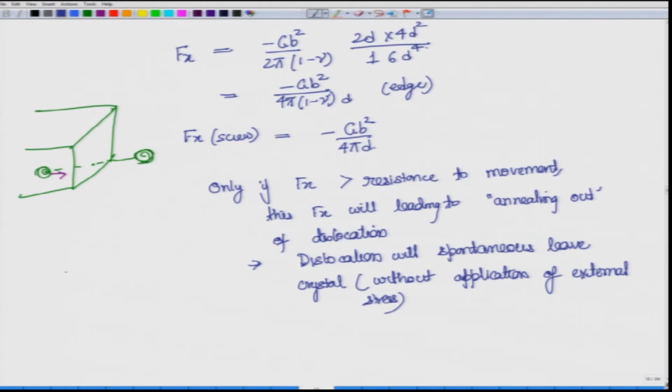So, let us say our crystal size itself is a few hundred nanometers. In fact, to exaggerate this concept, let me make it cylindrical. So, let us say this is a nanocrystal, a single crystal, and the diameter here is a few hundred nanometers, and let us say that only 25 nanometers of the surface experiences force large enough that dislocations can move.